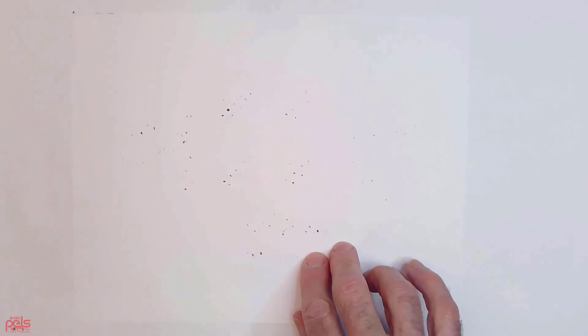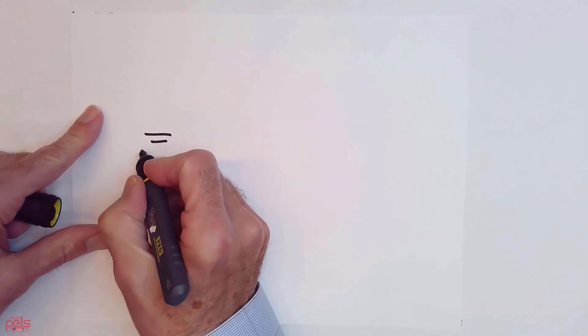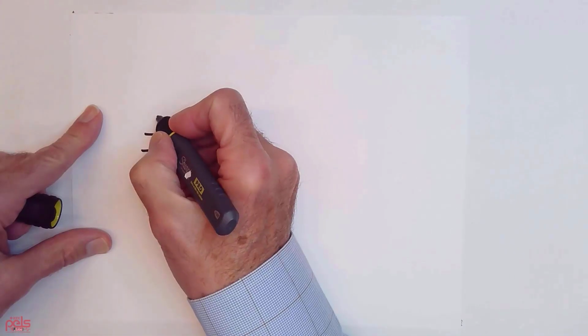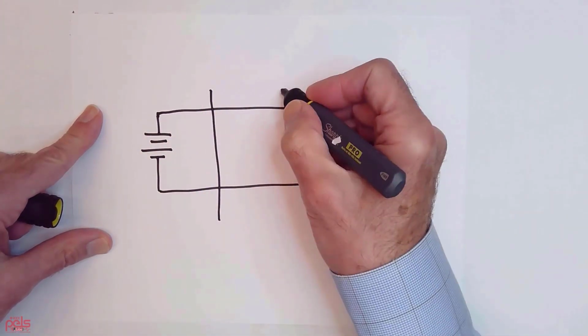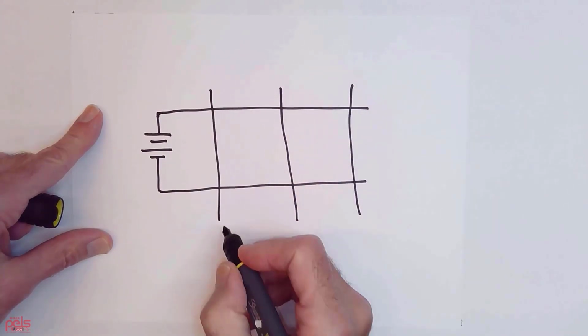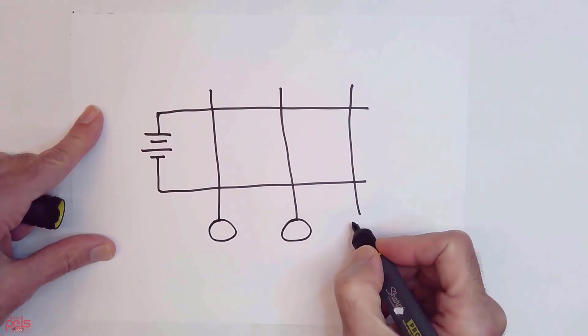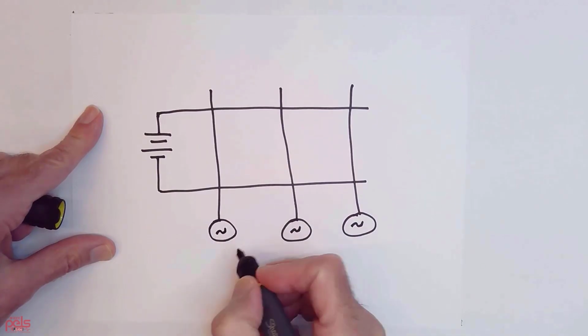And as you, I'm sure, would expect, in practice, we're going to have somewhat more complicated circuits. So the most typical voltage sourced inverter is going to have a set of 6 switches interfacing into a 3-phase load or a set of 3-phase AC sources.